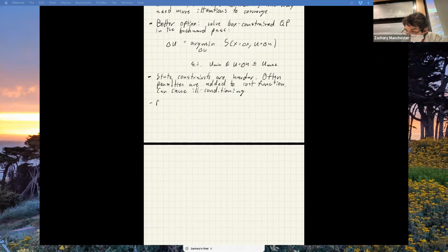A better option here is, like we talked about when we did general optimization, I can add a quadratic penalty to this thing really easily. I can also wrap the entire DDP algorithm in an augmented Lagrangian method. Remember, in the augmented Lagrangian method, we have quadratic penalties that fit super nicely into our quadratic action value thing. And I have a Lagrange multiplier term, which is a linear term, right? So linear plus quadratic, that's exactly what I've got in my action value approximation and cost to go approximation. So it fits in perfectly, and it makes it very naturally work.